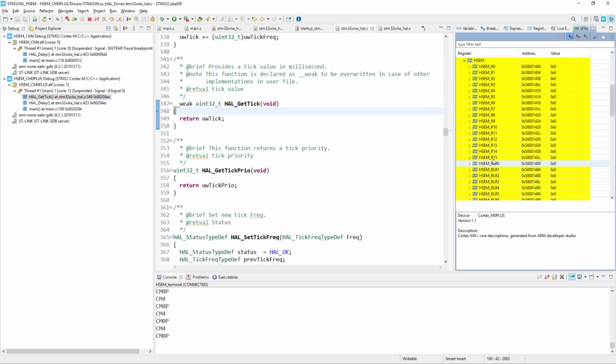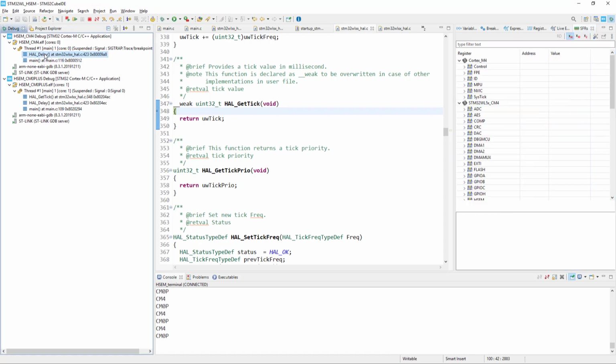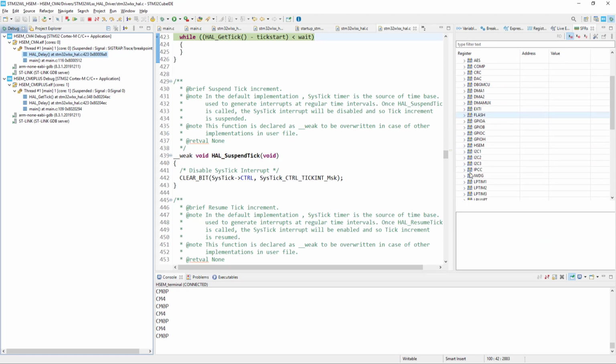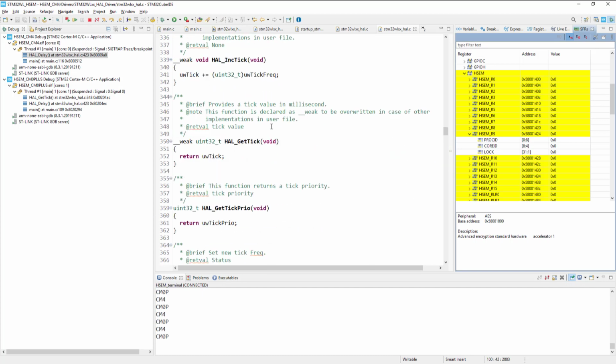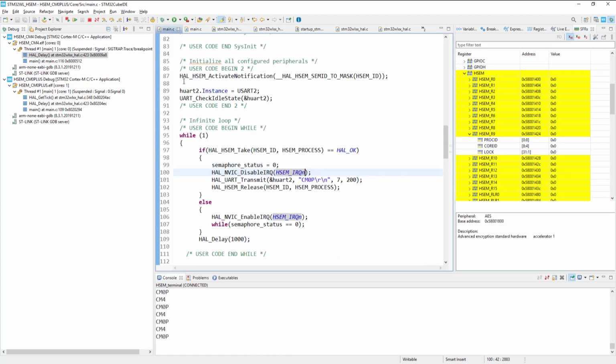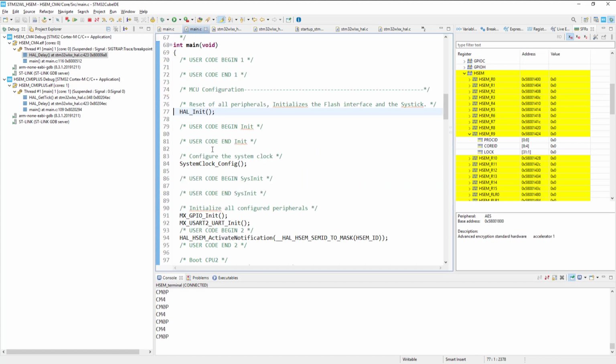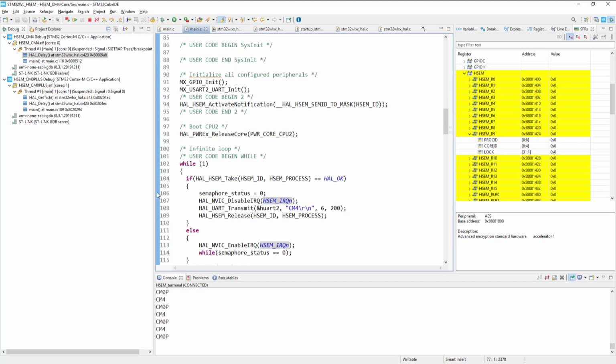We can check what we've got within the settings. So within the hardware semaphore 9, there is nothing at the moment. And within the Cortex-M4, it is released as well. So let's have a look once we set some breakpoints. So I would put the breakpoint just after, let's say, hardware semaphore take. So maybe in this line, in one core, and in the second core we will do the same.